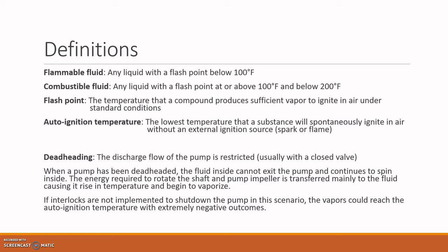Then the energy that's required to rotate the shaft and the pump impeller, generated by the pump motor, is transferred mainly to the fluid inside, causing an extreme rise in temperature that will begin to make the fluid vaporize.